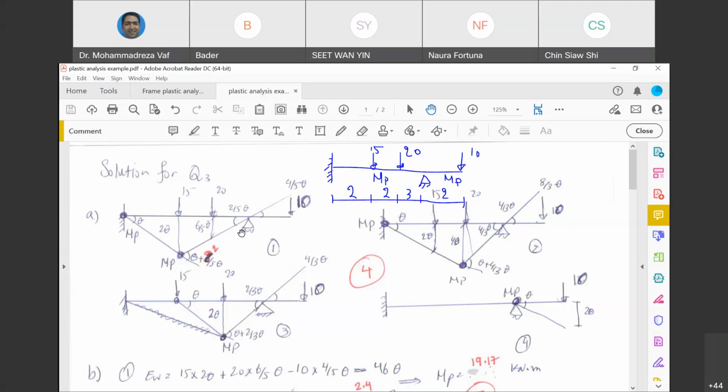One of them is similar to what you can see here, meaning one plastic hinge occurs here at the location of maximum bending moment. Another one, we assume, is going to occur under the point load of 15. And the second one is the pin support that can easily rotate. Since it can rotate, the cantilever part at the collapse condition is going to move upward. From the horizontal condition it is going to rotate upward. So this is why we can say that there is no work done here and we can easily see free rotation. So we have basically two plastic hinges, and one hinge here that can rotate.